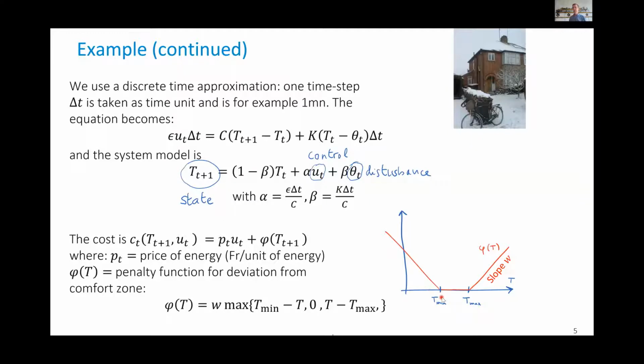And we say simply that there is no penalty if we are inside this band, and we put a penalty that we make linear to make sure our MPC will eventually be linear. So we put this penalty function here. We will need to discuss the slope. The slope here is the thing that will give more or less importance to this penalty function.